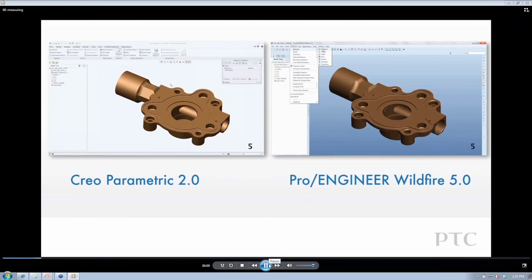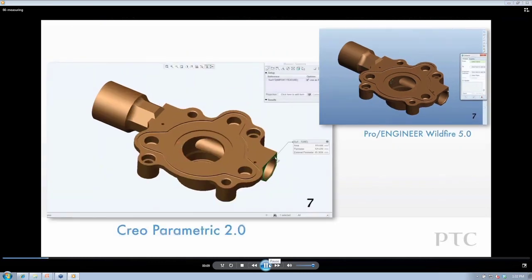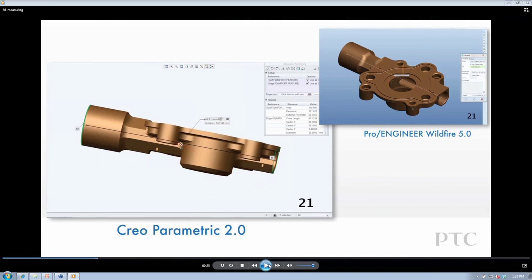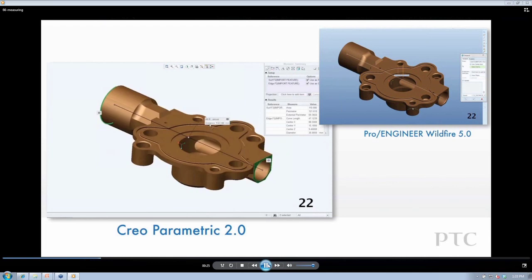But today in Creo, you just have one measure tool that does all of it. Every function is possible here. If I want to do a distance, there it is. It grabs the surface area of both those tags, and it gives me those tags available. It also gives me a nice result window. So I have the area of the surfaces I picked, I have the edge length, and I can grab all those entities, all those numbers, and drag and drop them onto Microsoft Excel because they're all cells.